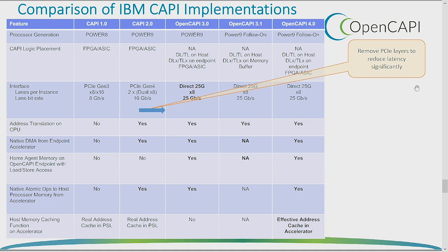The Power 9 you see here, for its memory, we have 2 versions. One of them is just traditional DDR. The other one is our proprietary buffered memory solution. So that same technology in our proprietary buffered one is what we've put into the OpenCAPI standard, which is what this 3.0 version is, and that's what we'll have in our next chip here. But memory bandwidth-wise, we're talking a standard DDR4 memory subsystem based around OpenCAPI.